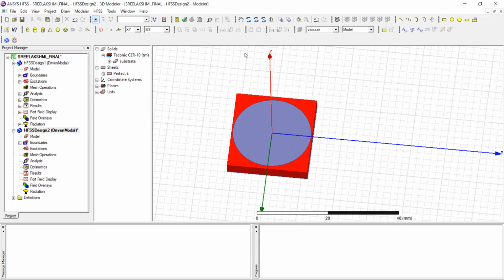It depends on which frequency we want. Based on that, we will select the connector. Also the weight of the antenna matters. If our antenna is heavy, we cannot go for SMA because SMA is a very small connector. If you want, I can show the pictures also for the SMA.